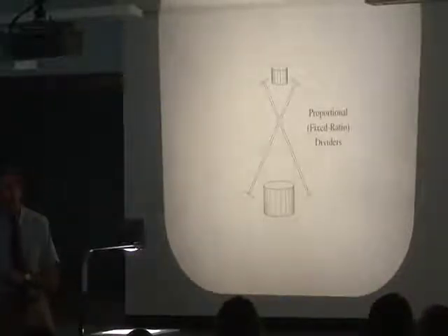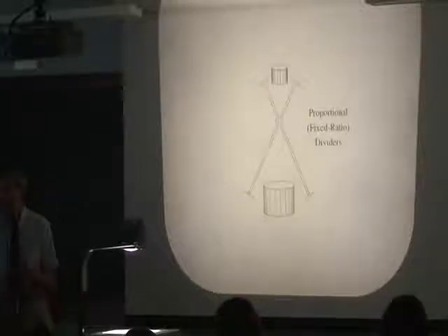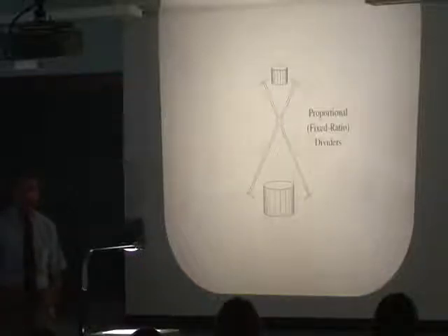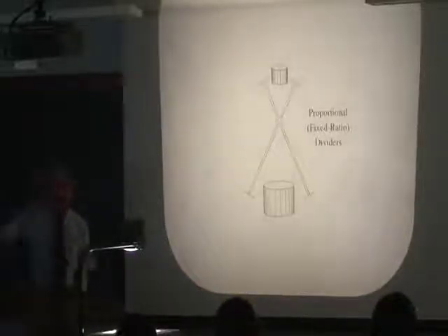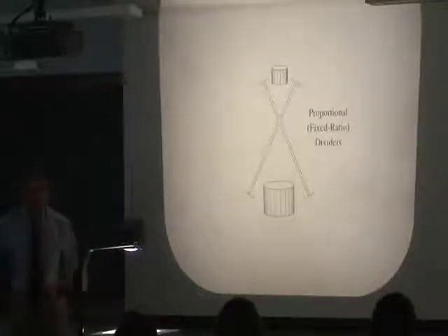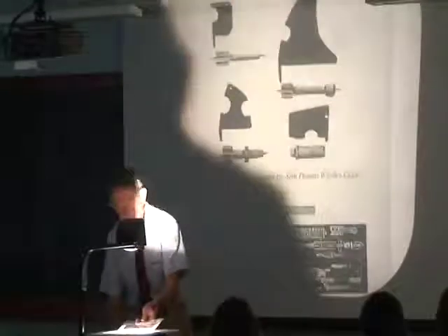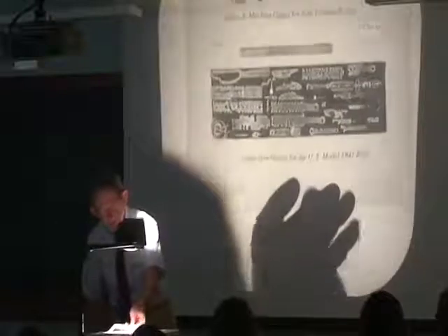Yet before that time, there were very strong efforts to have interchangeable parts. And the military, especially the American Army, put a lot of money for the time into people like Eli Whitney, who promised to make muskets and revolvers with interchangeable parts. This was about 1825 and 1830. Well, they managed to do it, sort of. And how did they do it? Well, with gauges. And gauges are like a fixed form of a proportional divider. It's not a way of measuring, but it's a way of controlling shape. Now, here are two different sets of gauges. Look at the bottom ones first.